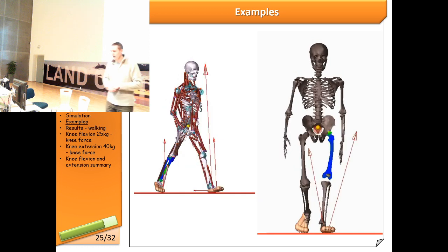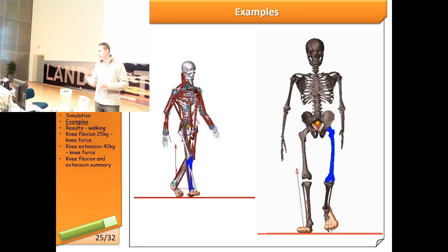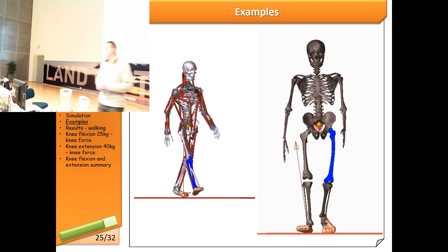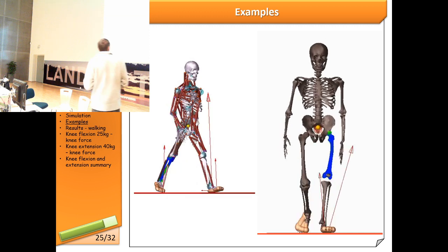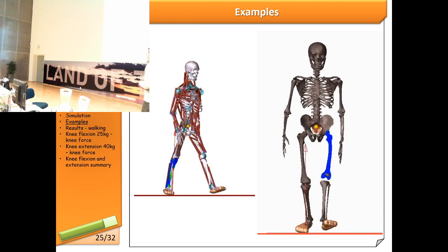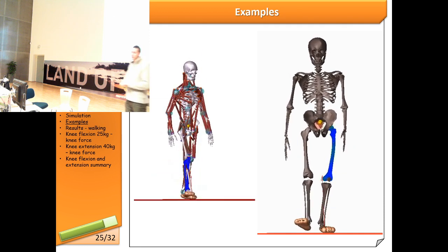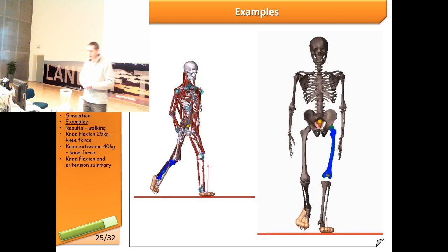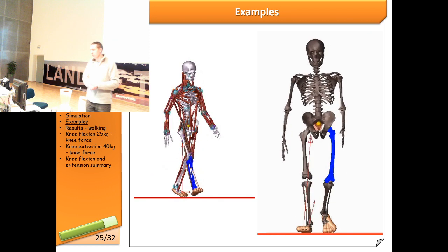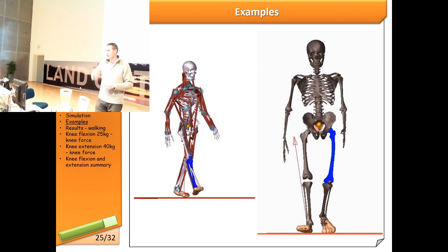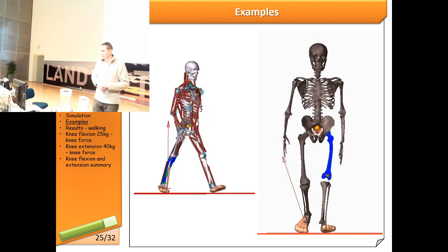There was a flexible tibia, and now the other guy started walking, and he has a flexible thigh. That was the thigh model shown in the previous slide. Again, we have muscles, but they are hidden to show the stresses. Here the stresses were mostly interesting in the neck section. And of course, the guy is walking, and we can see the ground reaction forces appearing. You can see that there's an impact always when he's landing on the heel, and then there's a little bit of increased force during the toe off phase.